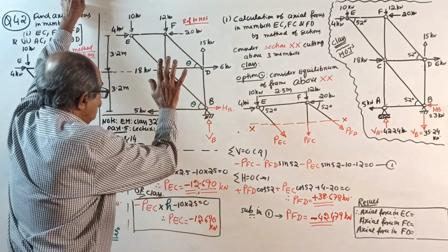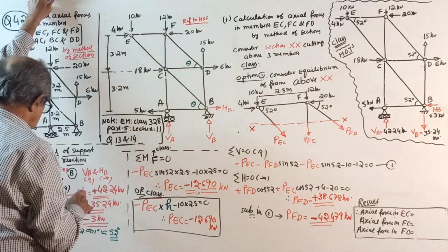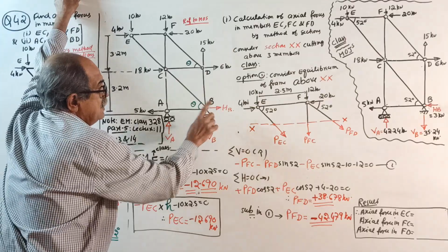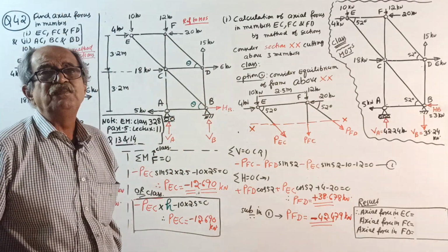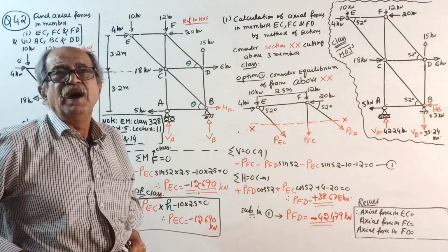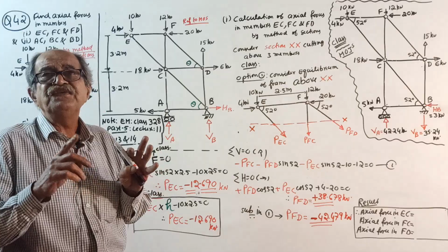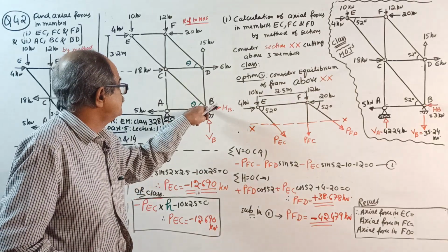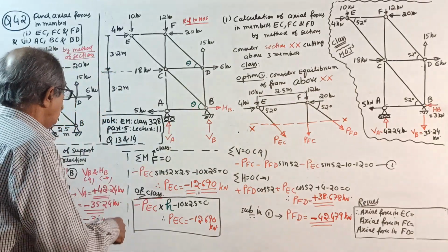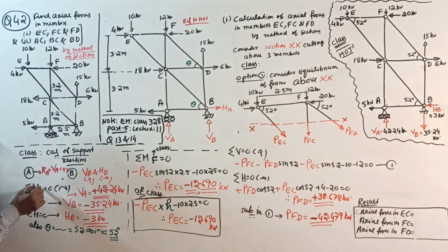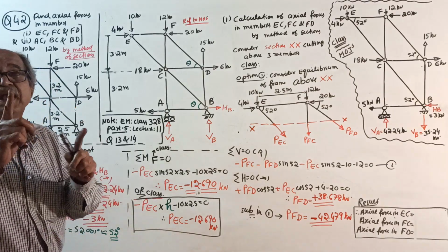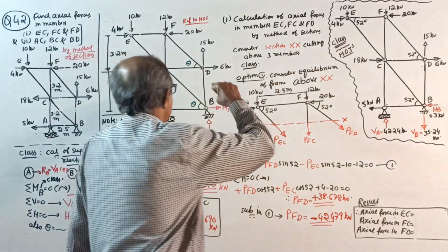Okay, now see. Correctly see now what to do. A has only one unknown. At B, 2 unknowns. I told from beginning of the subject, when you apply sigma M equal to 0, always take moment about the point where unknowns are more. Therefore, in this question, moment about B. See, where is B here? Moment about B. Why B? I told class just now. Okay, start. I am not going to write here anything. I am dictating. Listen properly. Finger should be at B.